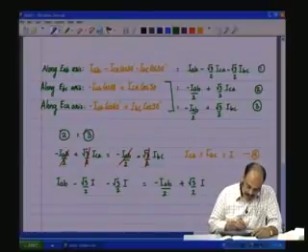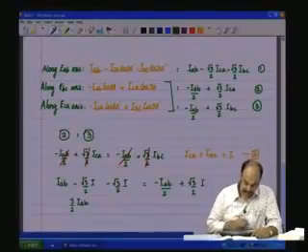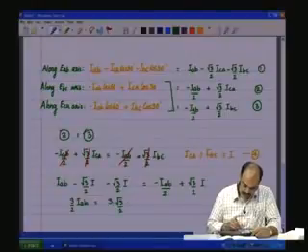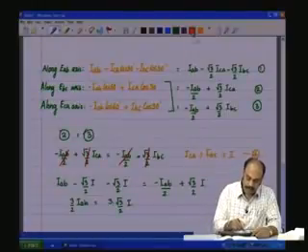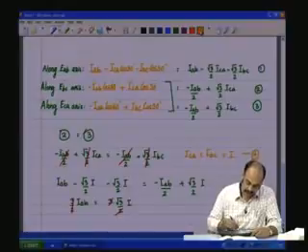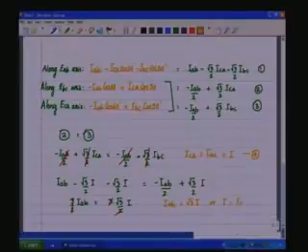So, now 3 by 2 I_AB, taking I_AB onto the left hand side and these onto the right hand side, you have 3 times root 3 by 2 into I. So, this leads to the following nice relation: I_AB is equal to root 3 I, or I should be equal to I_AB by root 3.